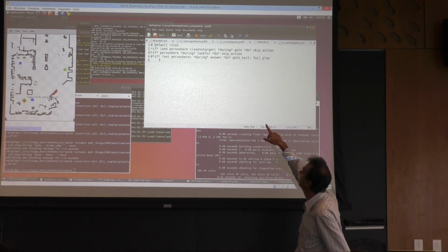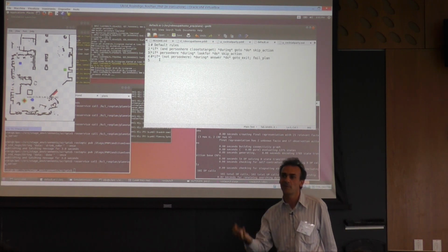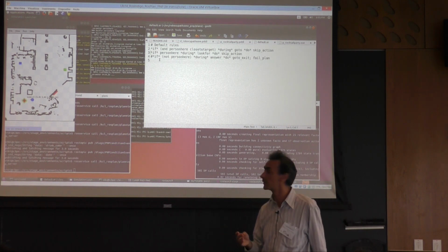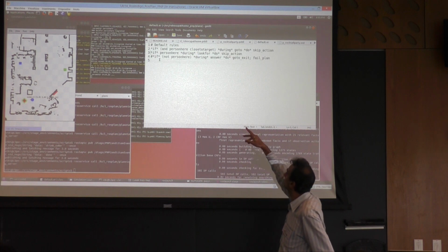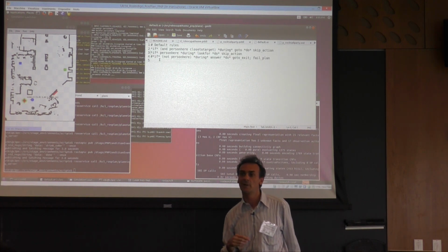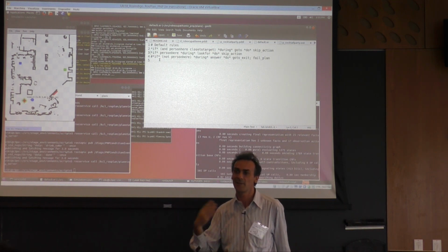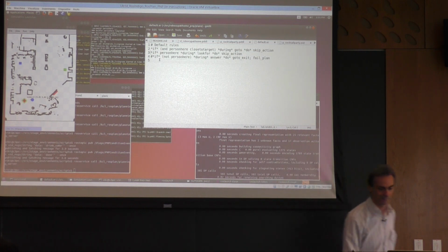And by the way, the next action is look for, but also in this case we can skip look for, because if you have a person in front of the robot, there is no need of looking for the person. So by adding these two execution rules, both the go-to action and the look for will be skipped. This means that as soon as the robot sees a person, it will start the phase of ordering something.